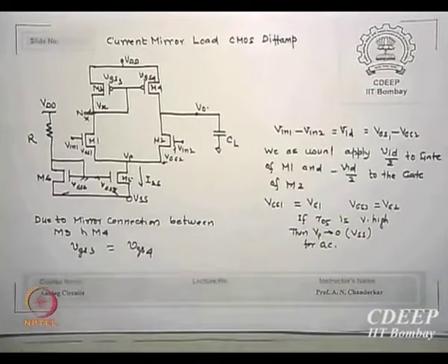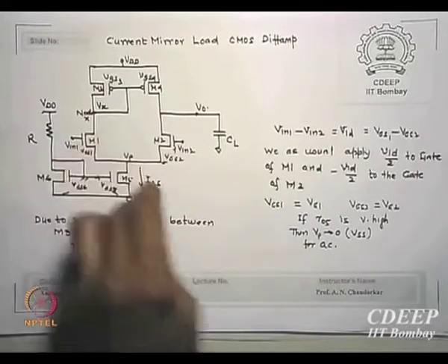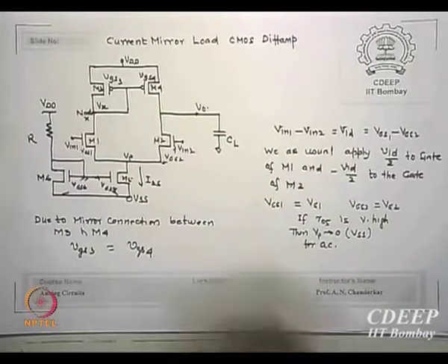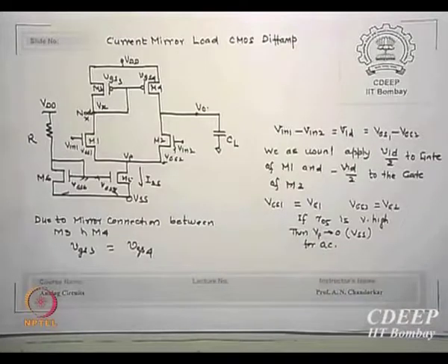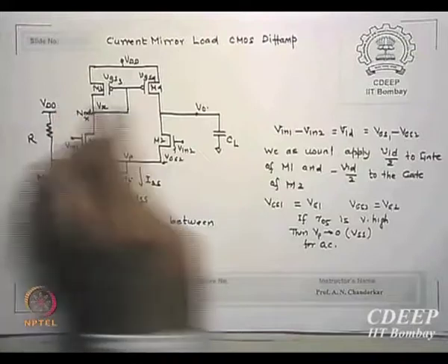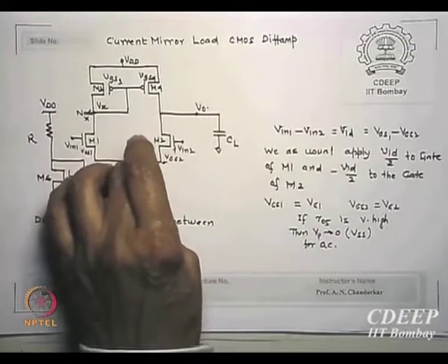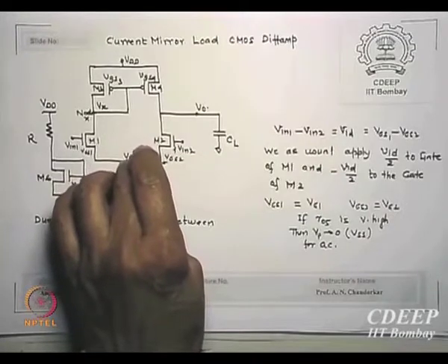I just now said the resistance of RO5 is large enough, and if the two currents go opposite, this potential can be treated equal to VSS, and right now for DC it is minus VSS, for AC it is how much? Ground. So we say Vp is close to the ground, is that correct? Because I am not sure whether they are exactly identical, so I may say okay, Vp is roughly close to the ground or can be treated as ground.